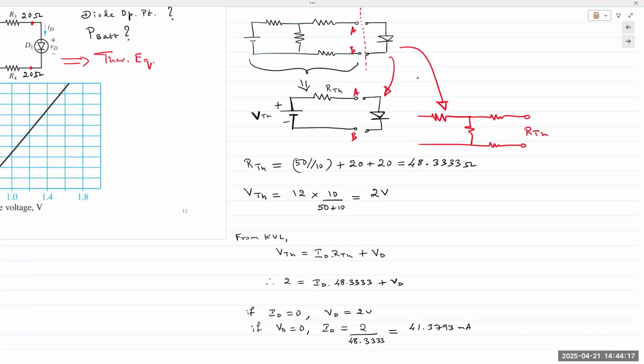So the point is, if we want to find resistance, we need to get rid of everything in the circuit except for the resistances, right? So all the sources that are there in the circuit, we replace with something. Voltage sources have very low resistance, almost amounting to 0, so we replace a voltage source with a short circuit, and we replace a current source with an open circuit.